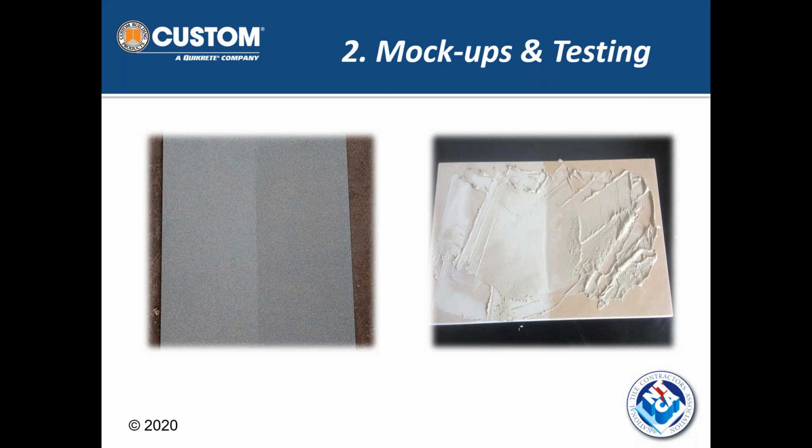Well, pre-sealing it not only addresses the issue of potential for staining, but it also allows you as an installer to have that working time, that open time to work with the materials and get the coverage, get the ease. I can't demonstrate that in a picture, but the ease of grouting a pre-sealed surface is so much nicer. Trying to just take that float and put it on the stone, I could feel it grabbing. It was literally the moisture being sucked right out of it.